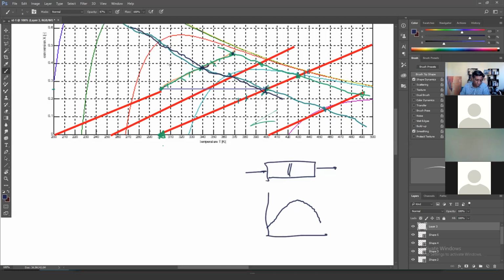In your PFR, you've got differences, you've got zones where the rate is lower and so on. But the way we've chosen it, we've chosen to step over the maximum. So at least on average, it's a nice high rate in between. So those are good criteria. That is a good choice for the design of these two reactors.